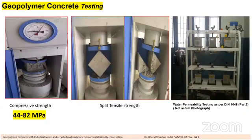Now you can see the actual photograph, on the very left side, where we have tested. A compression testing machine is there, and we have tested the geopolymer concrete cube. Compressive strength test was done, then split tensile, and then water permeability tests were also performed. And the interesting factor is that we have developed geopolymer concrete with varying compressive strength of 44 to 82 MPa.